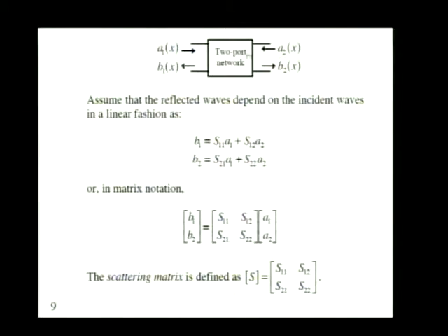A1, well, I guess I could produce an A1, a wave incident on the two-port, by hooking some sort of a source up to port 1. And we want to make sure A2 is equal to 0 in order to be able to measure S11 or calculate S11.